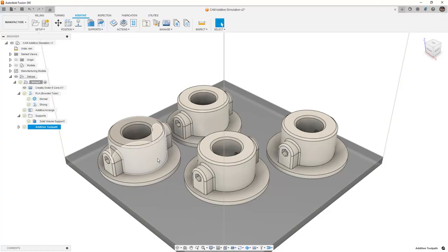But keep in mind that there are a lot of settings that need to be validated and reviewed when you're setting up a 3D print. Once you've used this process and you've set up a couple of materials, the process goes relatively quickly. However, the initial prints will take a little bit of time for you to figure out things like your print speed settings, the temperatures, and some of the other general settings that you need in order to create your 3D prints with the accuracy and tolerance that you desire.